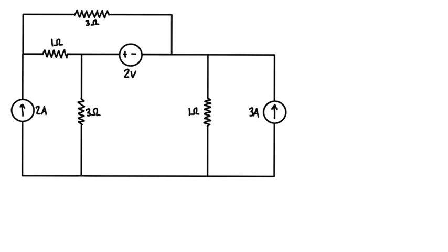this entire circuit. So to get started, what we would do is draw on a ground. It's going to be helpful to draw it in the node that's connecting to the most power sources and most branches. It's often helpful to draw it connected to a voltage source. It's up to you, but in this video I'm just going to go with the example down here, just so that we can isolate the voltage source with the method of supernodes, just so you can get an example on how that works. But basically that means that we're going to know this voltage here. This is going to be 0 volts.